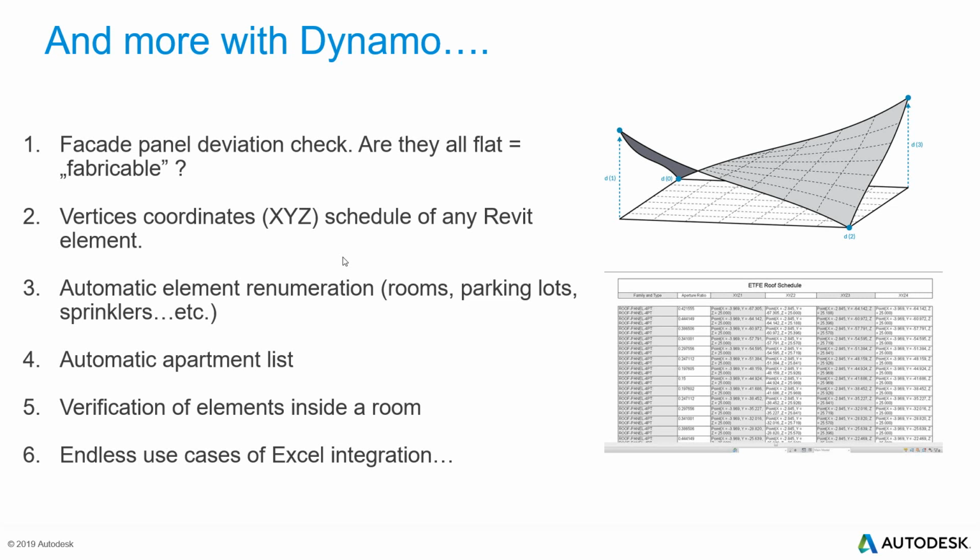You can use Excel both to read data, like we did in the video with FormIt, and to push data from Revit or FormIt to the Excel sheet, and make a schedule, and of course make the schedule dynamic, right? You can put the execution mode to automatic in Dynamo, and then anything that changes in your model will be automatically updated in the Excel sheet.